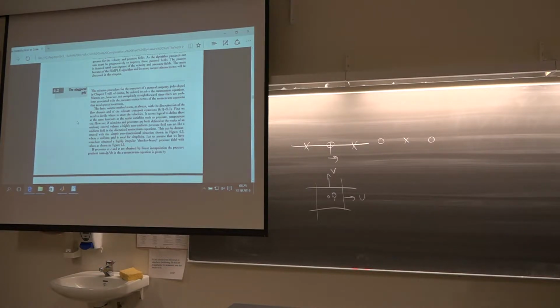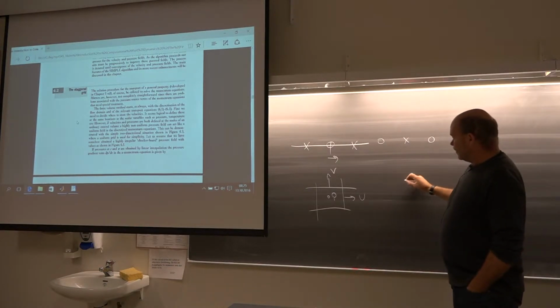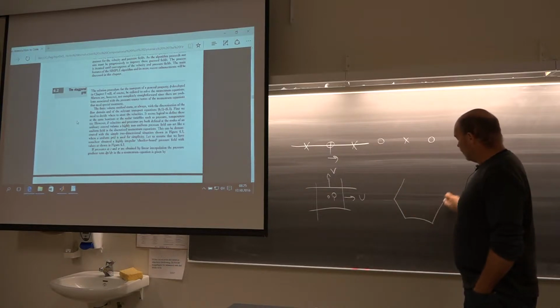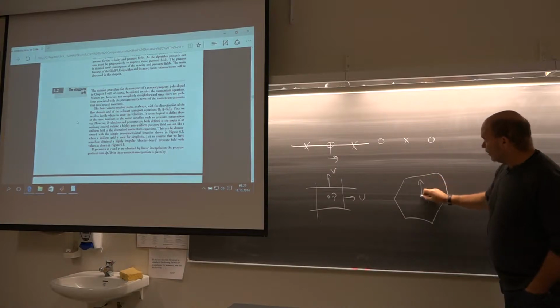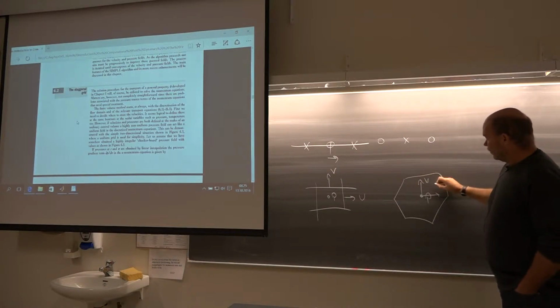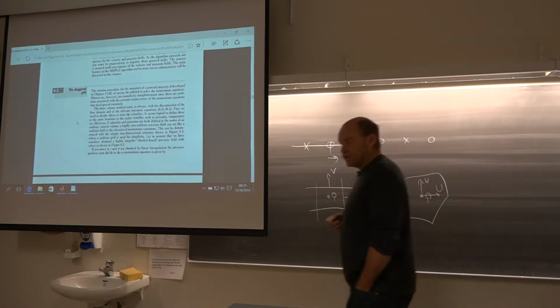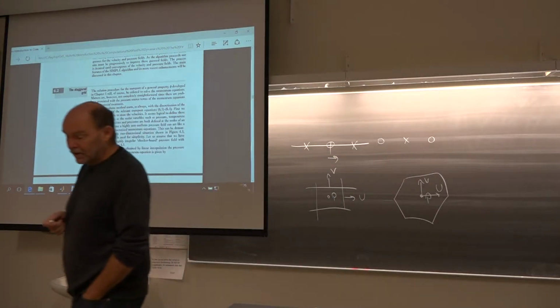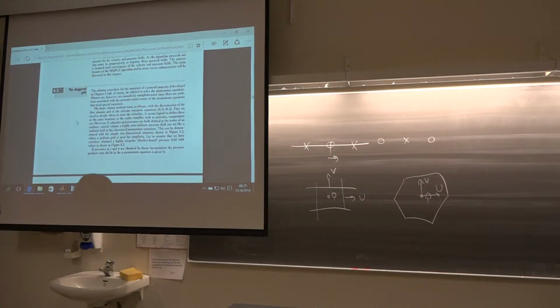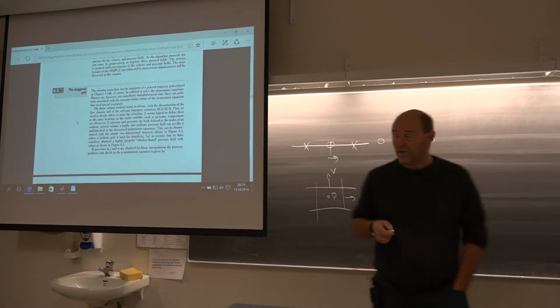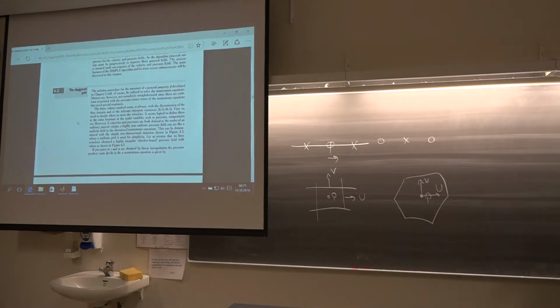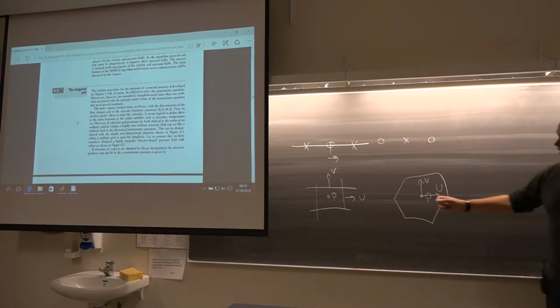But in OpenFOAM, we know that inside one single cell, we have the pressure and we have the velocities. So that is the co-located mesh system. That's what we are using in OpenFOAM. So how can that be? Well, you have a trick called Rhie-Chow interpolation to just avoid this.